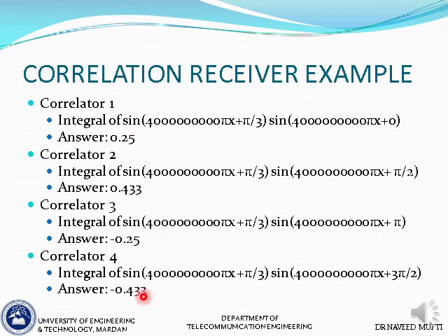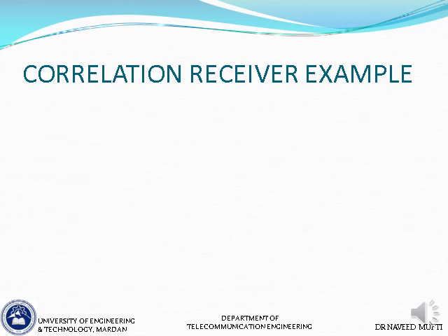And as we have studied, the receiver uses M correlators and determines the numerical outputs, and then makes them pass through a comparator, and then selects the correlator with the highest value. Okay, so after all values are calculated, let us go on to the next slide.